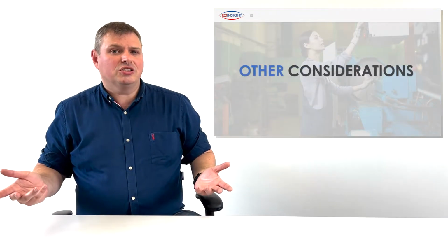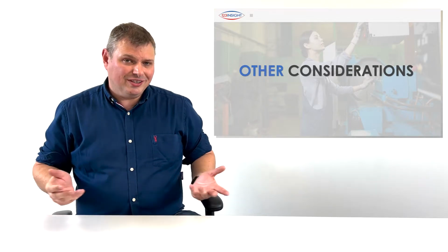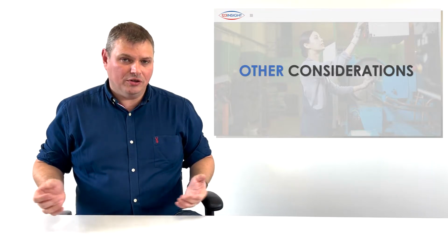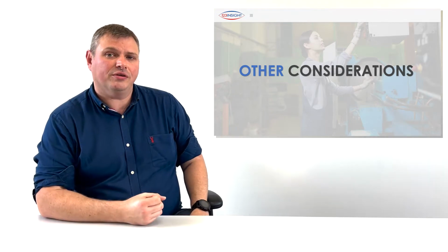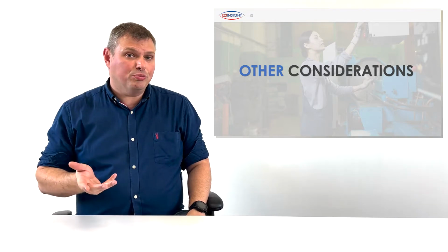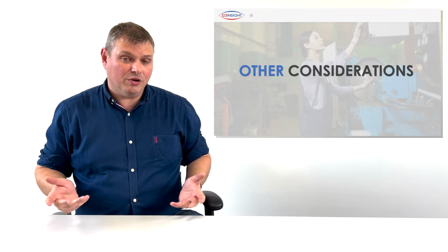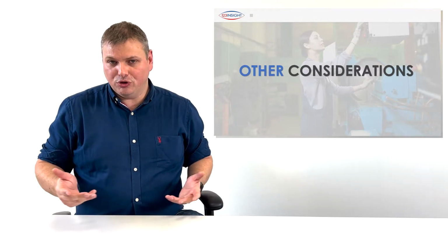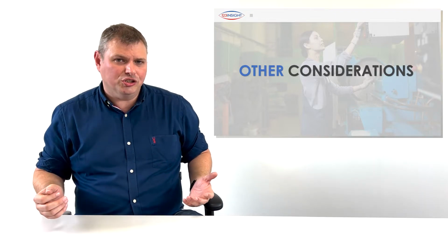Other things that you need to consider are things like shelf life of components for manufacture. Certainly things like glues, resins, thinners would have to have controlled shelf life and the ability to document and show an audit trail of that shelf life. Then for the purchasing teams, there's the flow down of information to approved suppliers, so a complete specification for suppliers as to what they should supply, the ability to maintain approved supplier lists, and the ability to control communications with those suppliers.